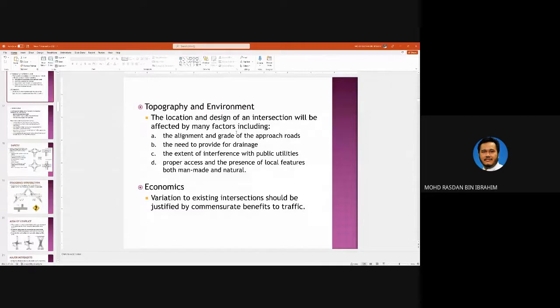Okay, does the point that you have chosen give you a good intersection or not? I believe one of the intersections is very close to a bridge, because the existing road is actually crossing a river, isn't it? In that case, definitely at that point you are going to have a bridge. So is it safe to create an intersection very close to a bridge or not? Your first alignment is going to be an alignment that has a bridge, meaning that you have to construct a bridge.